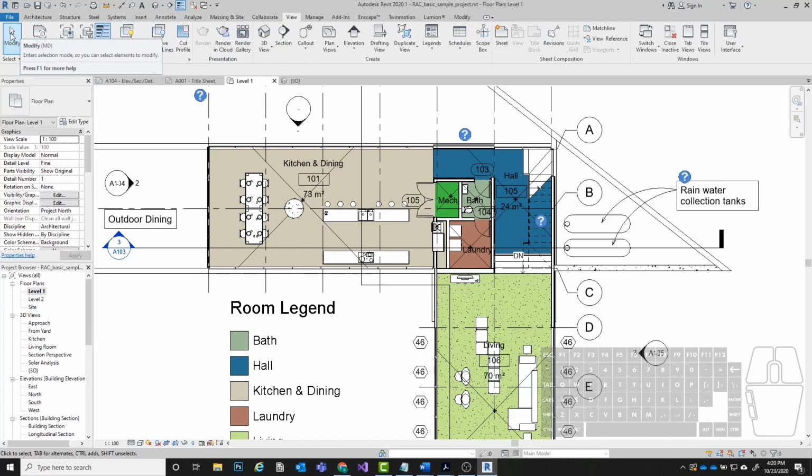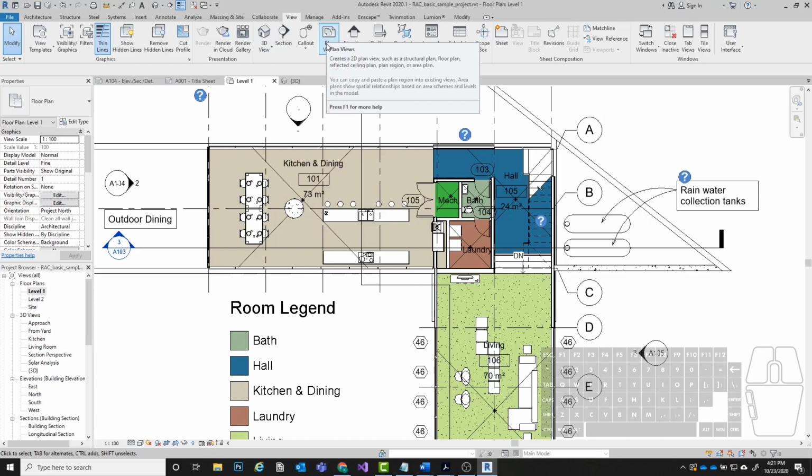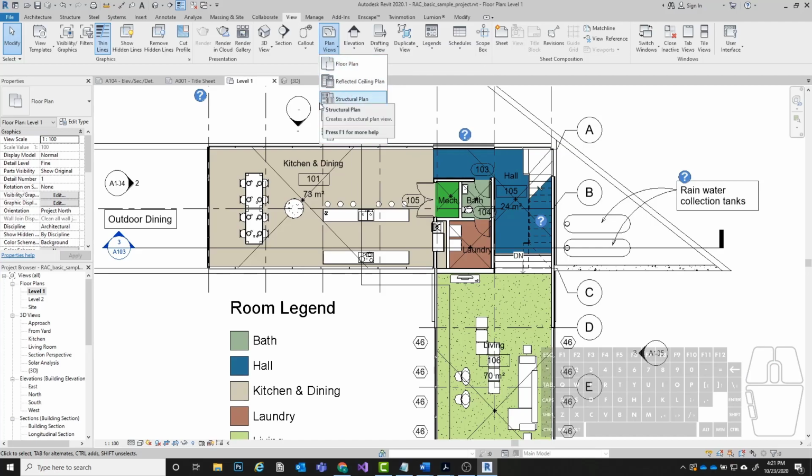Views are something that we will get into in greater depth later on. You don't need to know too much about this, but we're creating different types of views. We have 3D views, section views, and different types of plan views, like RCPs, reflected ceiling plans, regular floor plans, and structural plans. And then elevations, like our elevation markers here and here. We have framing elevations, regular elevations, interior elevations, and exterior elevations. We will get into those later.